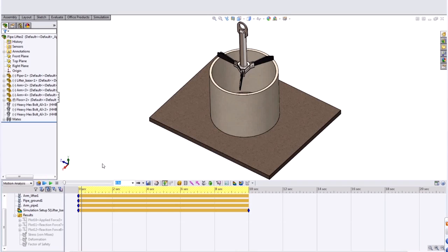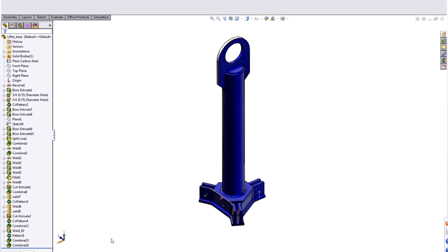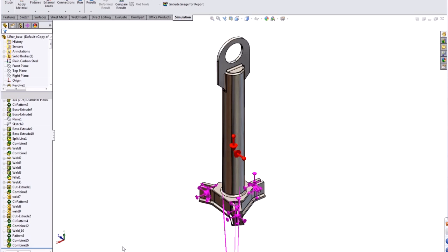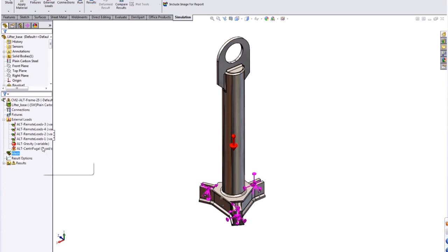And it looks a lot like nothing happens. This is often where people are going to bail out of here. But what it's done is it has loaded a new analysis study into this particular file. Right? This analysis study includes these weird-looking remote load variables, but these are the loads transferred at every connection point that this part has with other things in the motion analysis.